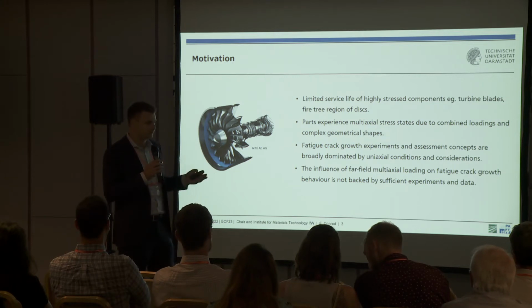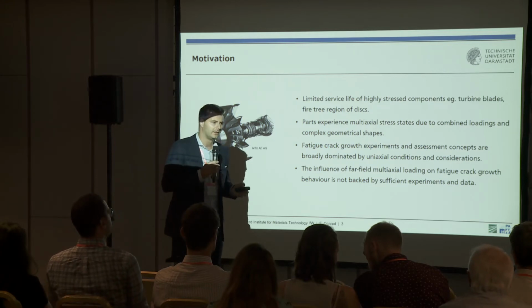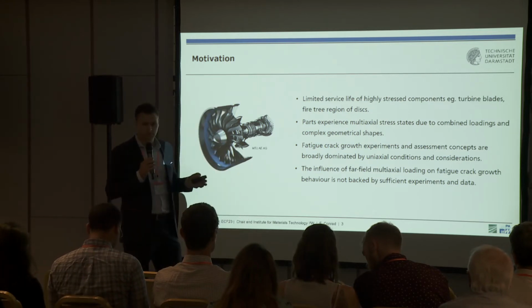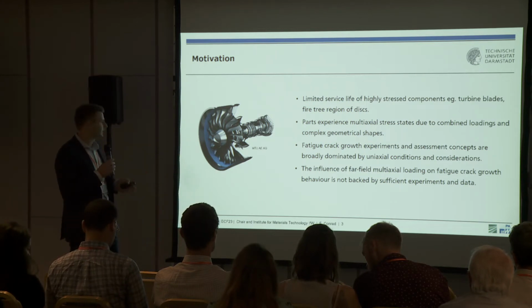We have a centrifugal force, we have resonances, imbalances, flow separation and so on. And on the other hand, we have a complex geometric shape. So this all leads to the fact that a turbine blade is multi-axially loaded.